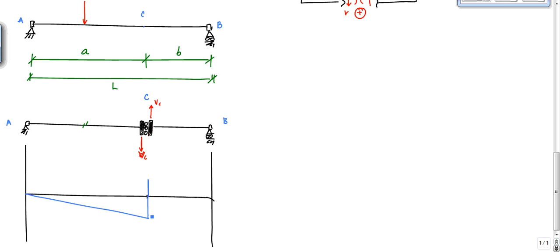And this would rotate up. Member BC would rotate up and look like that. Okay? And this total displacement is 1. That's unity, or 1. That's that unit displacement that Muller-Breslau talks about. This is the general shape of the influence line.